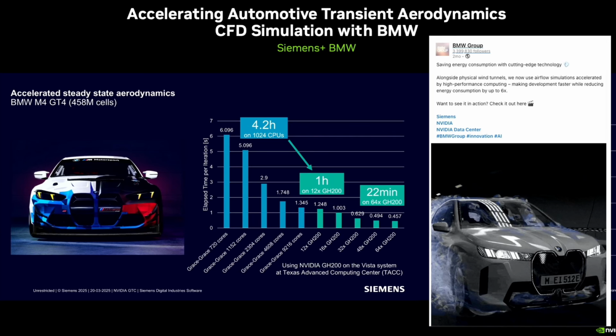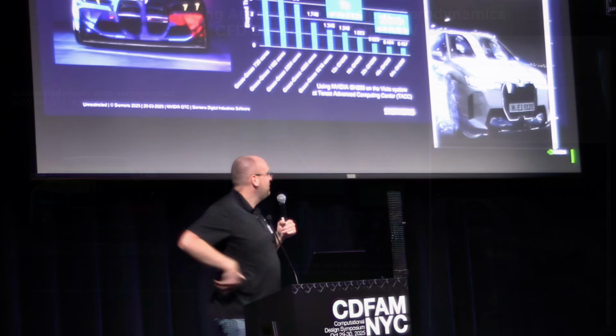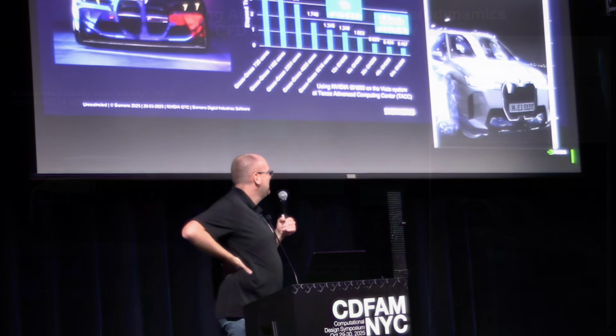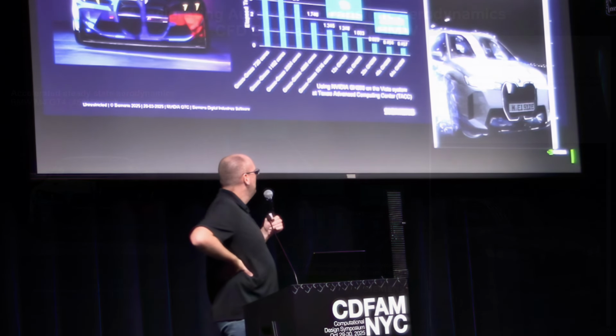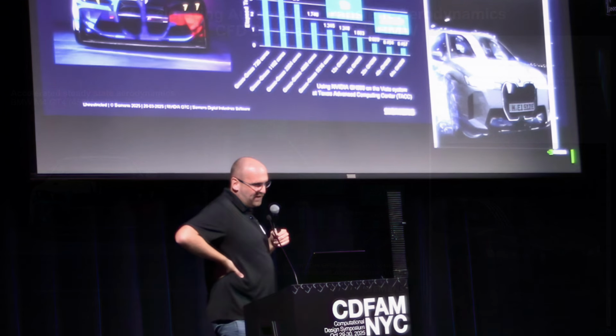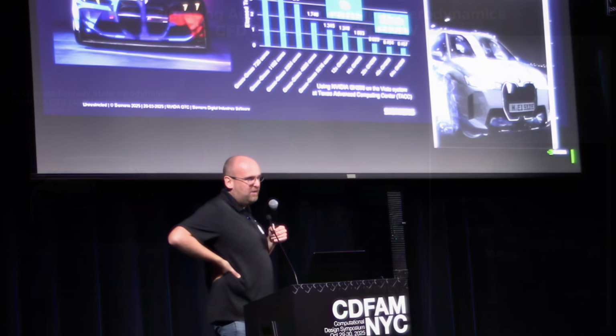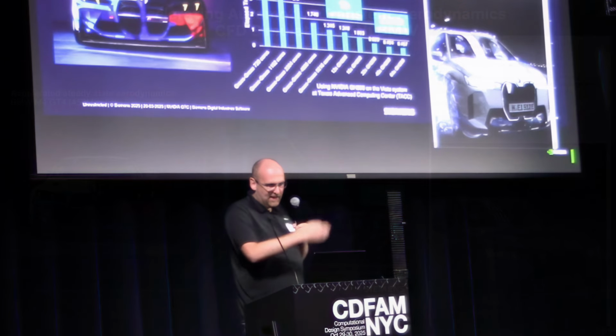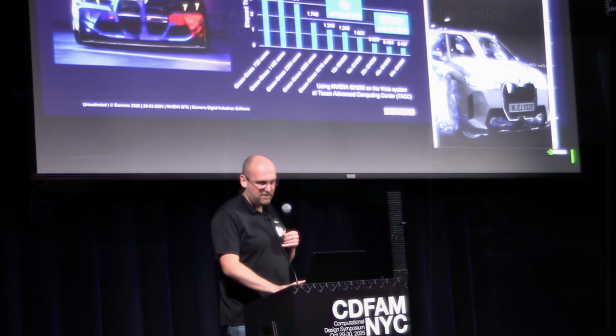We're working with them at the moment on thermal management, because that's a tough problem: you've got the external aerodynamics, plus you have to model the interior of the engine bay as well. So you have loads of geometry inside that engine bay because you're modeling all of the thermal properties of the things heating up and cooling down. You've got to run it for long transients. If they do the full fidelity simulation, it can take 7 days to run on a pretty decent HPC system. If they can get it down to 2 days, they'll do that in production, as part of their regular production work. So getting this kind of high fidelity simulation faster has a real effect.